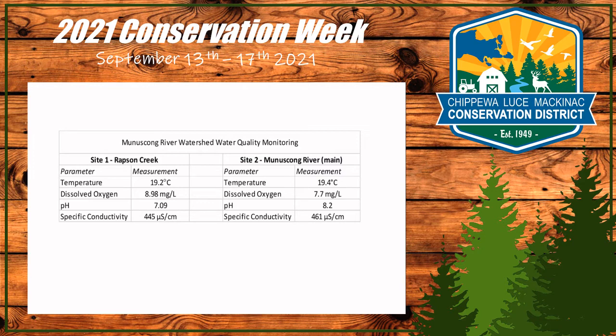aquatic vegetation. There were potamogetons, pondweeds, there was elodea, which is water weeds, and different species of emergent vegetation in the area. And typically in these streams and rivers, if we see a lot of vegetation like that, we'll see higher dissolved oxygen because plants photosynthesize and replenish dissolved oxygen in systems.